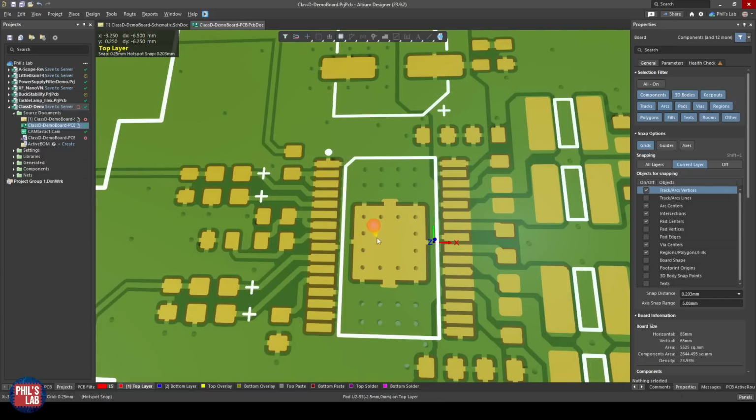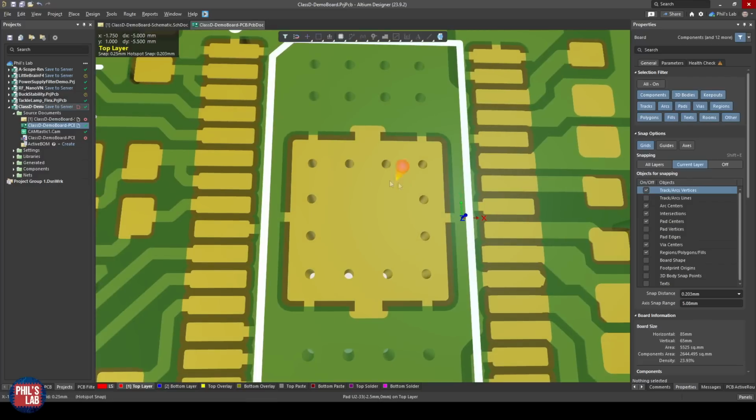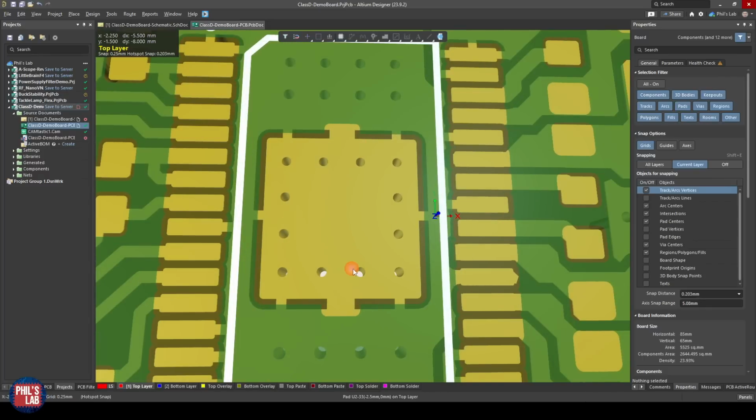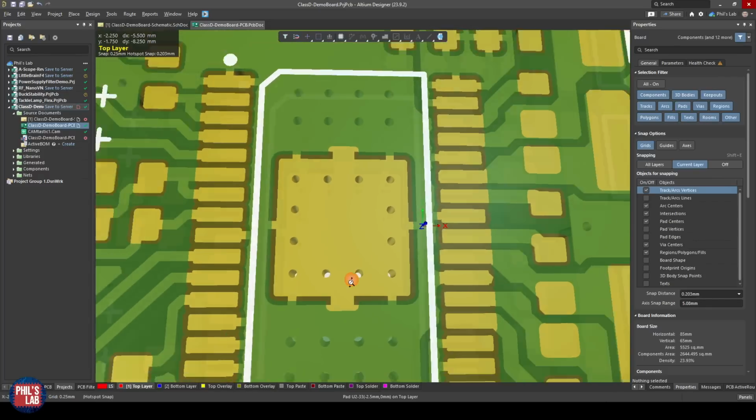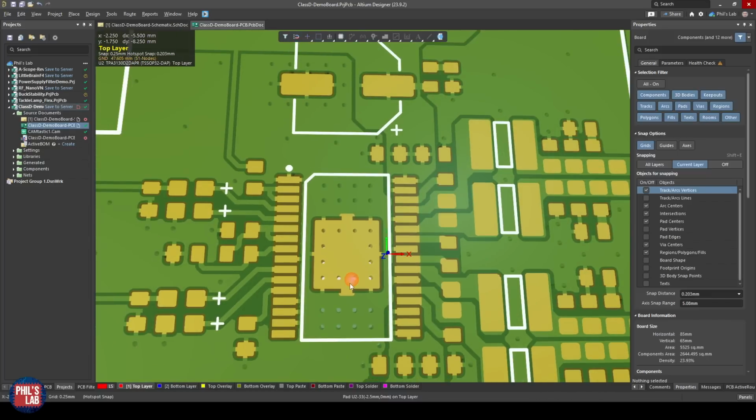So we want vias directly down, many vias in parallel to reduce inductance and improve the thermal characteristics. But also we don't want to place too many vias in this exposed pad because otherwise we get problems when we apply solder paste and we get problems with solder wicking. So the pattern I usually like to do is keep a tiny bit of space in the center of my exposed pads and place vias scattered around. And this, for this fairly low power IC, is still fairly sufficient for 15 watts, and keep in mind the efficiency of this IC is over 90%.